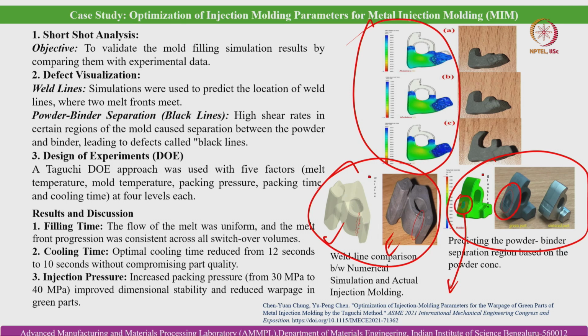So, you can see that based on the process model, we could optimize the injection pressure, we could optimize the cooling time, we could optimize the filling time. And then these optimum values can lead to the development of defect free parts.